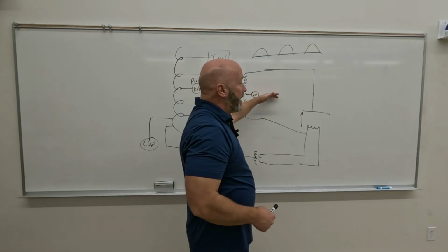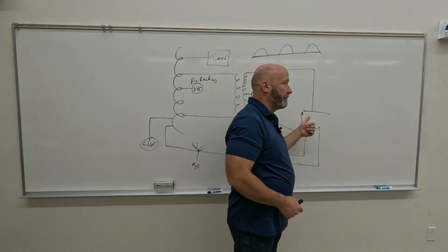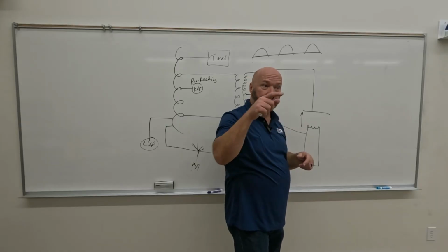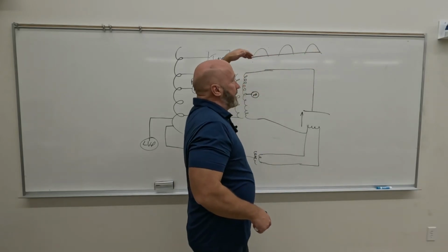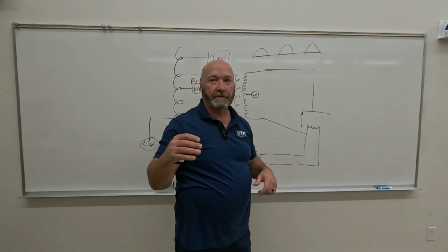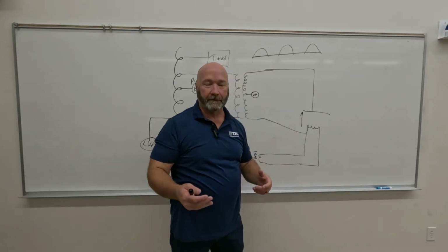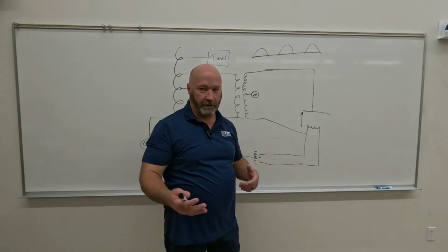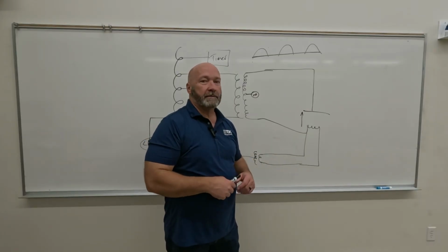So we do have machines where the X-ray tube actually becomes the thing that changes alternating current to direct current. It's pulsating direct current, right? Each one of these things is a pulse. It's only going in one direction, but the kilovoltage on those units is high enough that it would never become an issue. So you only see that in dental machines, okay? Even mammo, which shoots generally with no higher than about 40 kVp, is still going to use rectified machines, but dental units,